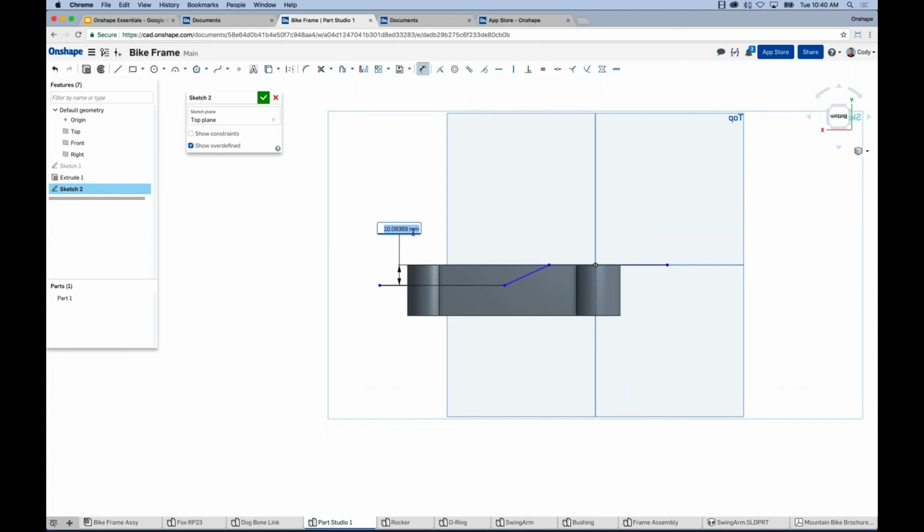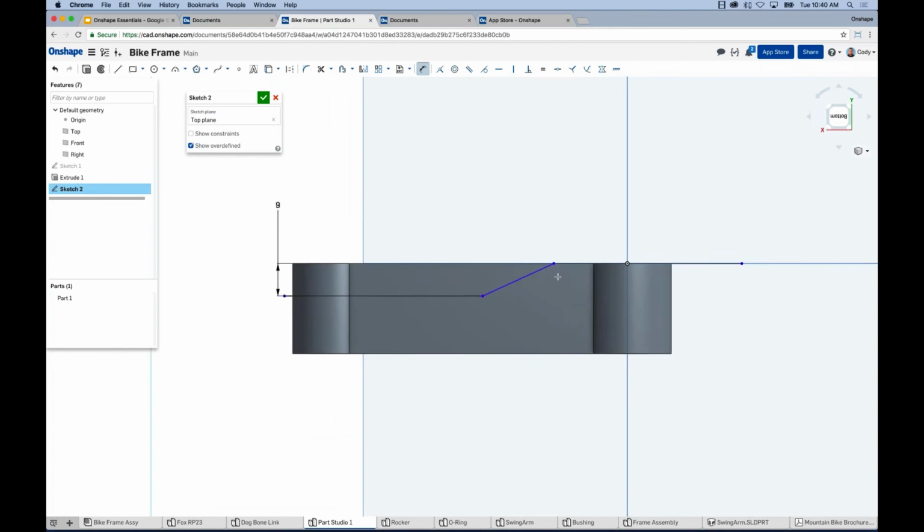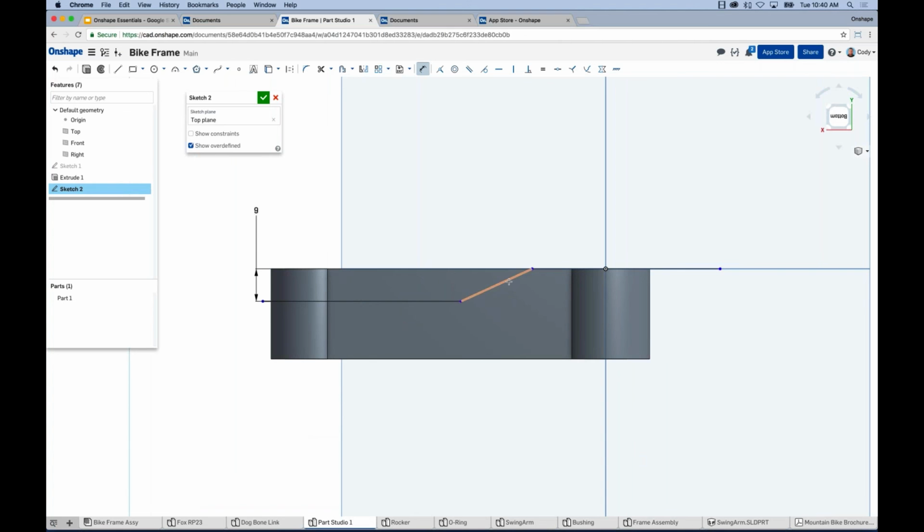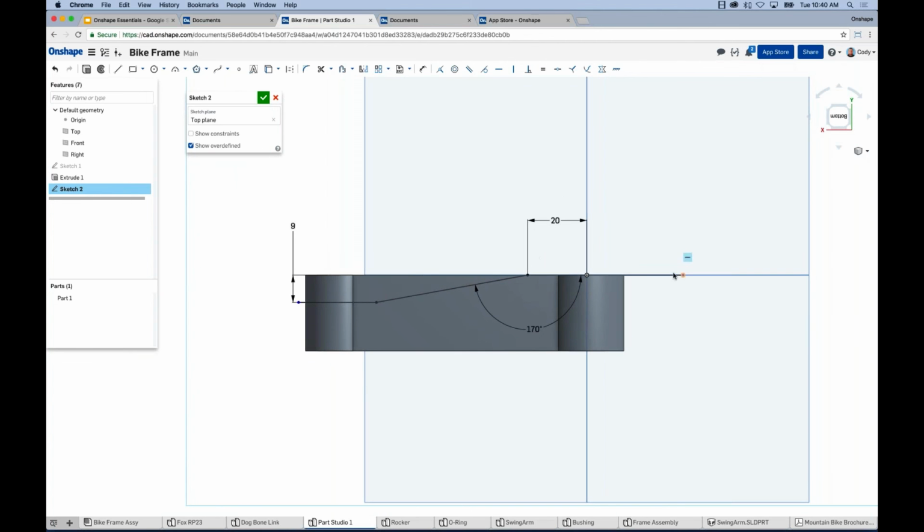Now, the thing I always like to mention is, it should be an intuitive, easy to use experience if you've come from other CAD systems. So, if I want to add a dimension for an angle value, just select 2 lines that aren't parallel and it automatically gives you that value. If I want to dimension, for instance, from a plane to a point, just left-click a plane, left-click a point, and there you have a dimension. So you don't have to be really picky about the things you dimension to. Just simply select the dimension command and start left-clicking the things that you want to control.